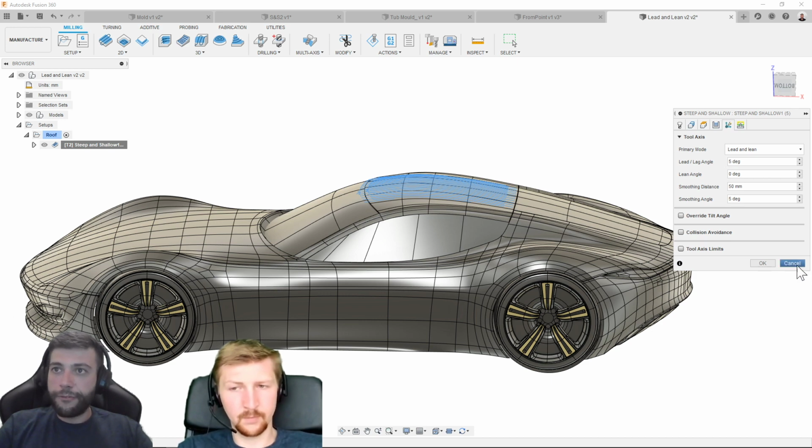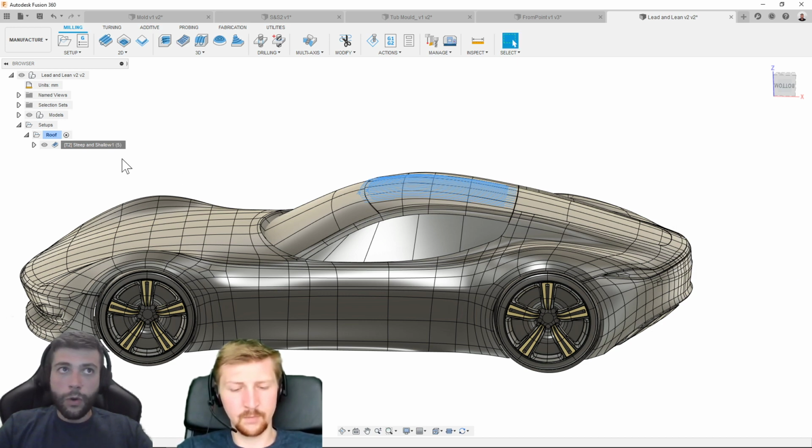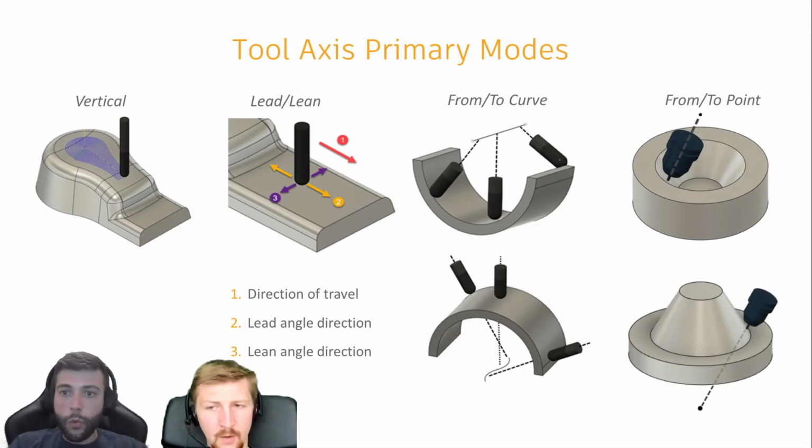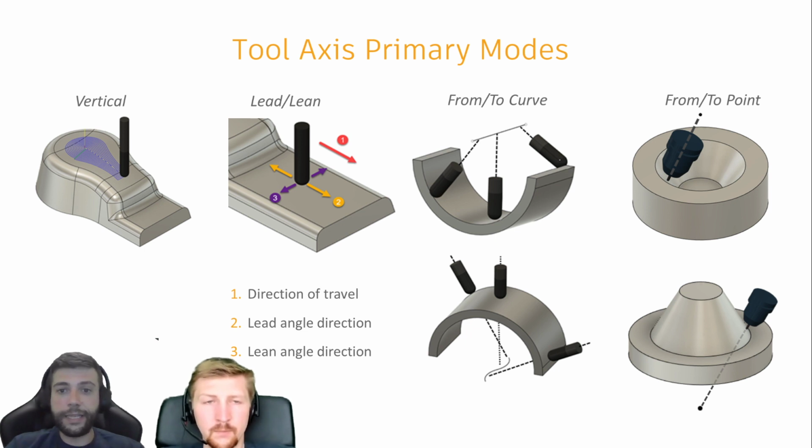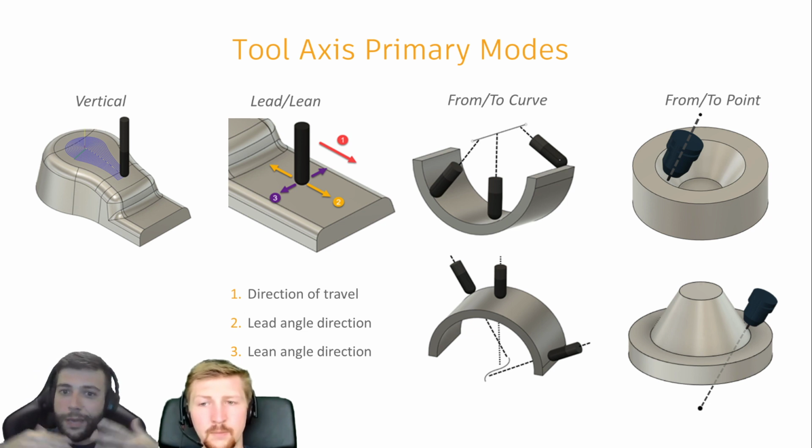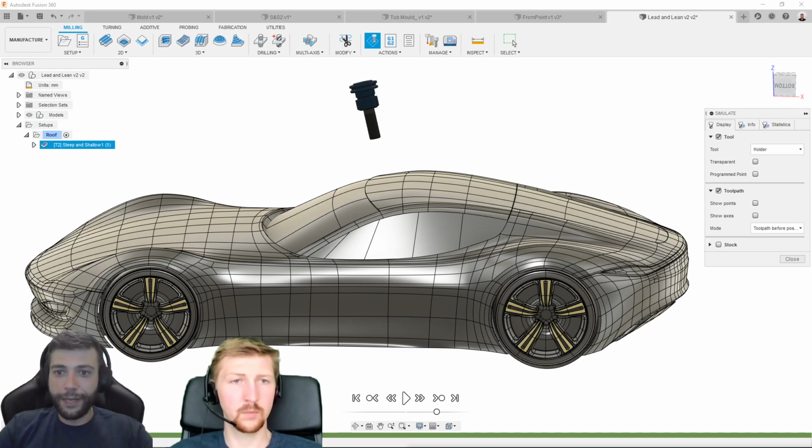So in this case, I've got 5 degrees. What would that mean? Again, I'm sorry to dwell on this, but we're going 5 degrees in the direction of cut. So the tool is going to be tilting. Let's take the pencil again. Just 5 degrees in the same direction of cut. In that way, we're going to allow ourselves to not cut with the center of my tool. It's not going to be a huge problem, but you're not going to get a good surface finish. Very simple. As Richard said, that part geometrically, mathematically does not spin.